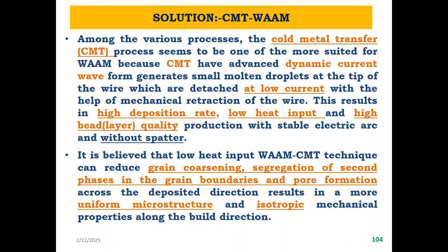Among the various processes, the CMT process seems to be one of the more suited for WAAM, because CMT has an advanced dynamic current waveform which generates a small molten droplet at the tip of the wire, which is detached at a low current with the help of mechanical retraction of the wire. The result is a high deposition rate, low heat input, which is a very important one, and high bead layer quality, produced with a stable electric arc and without spatter. Spatter is the reason why we prefer